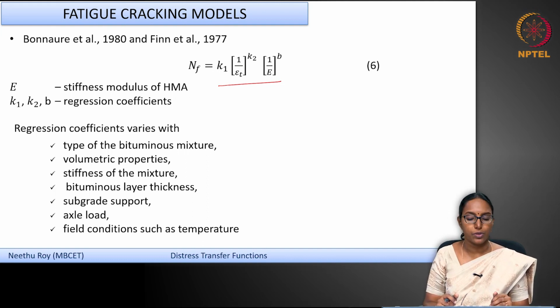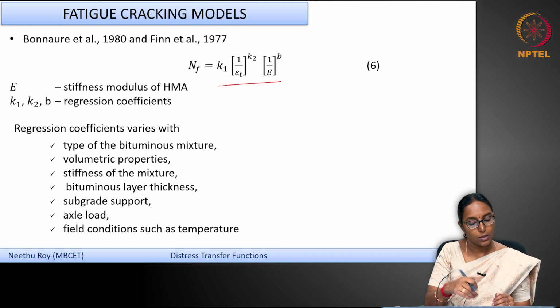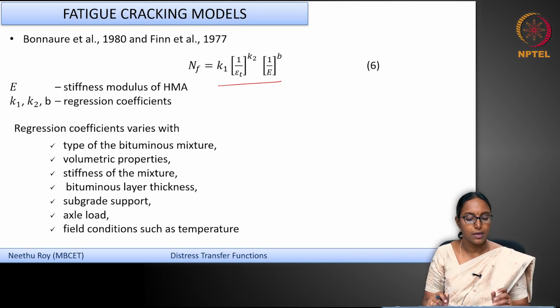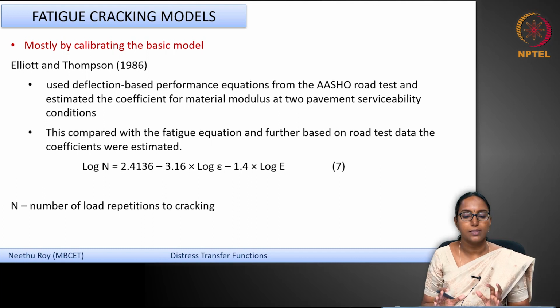Now, when it comes to K1, in addition to these factors, it will depend upon various parameters like the bituminous layer thickness, what is the axial load that is coming, what are the field conditions, environmental conditions and so on. Okay. So, all these models are developed based on the same concept or the same basic model.